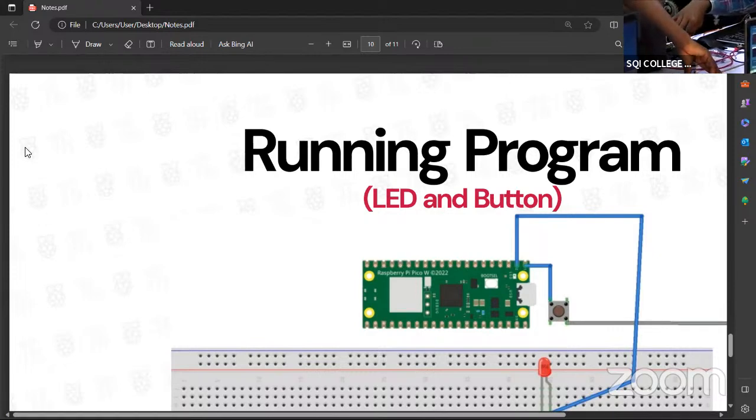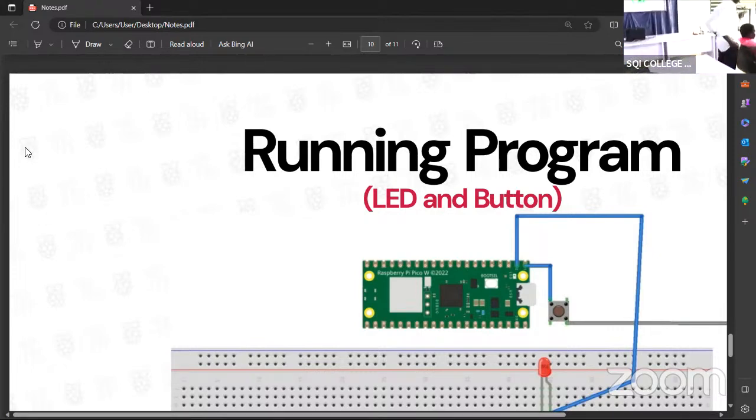Now, this type of button is called the push button. This kind of button is already connected together. That means when you push the button, it is going to give out something called a state 0. That is off. When you push that button, that is going to trigger off. And in that state, you have to ensure that your code is set to automatically high.